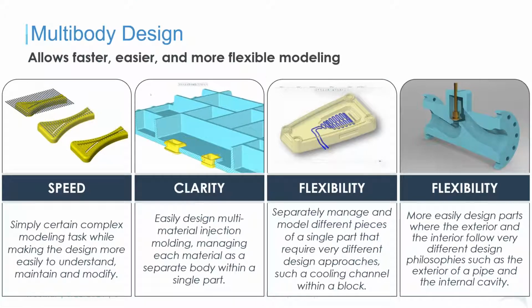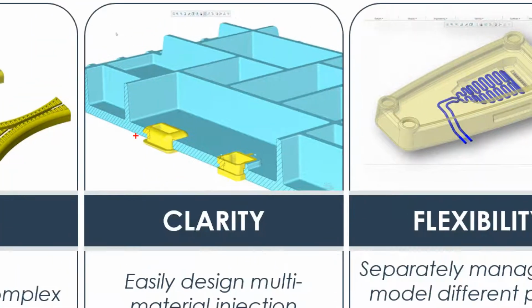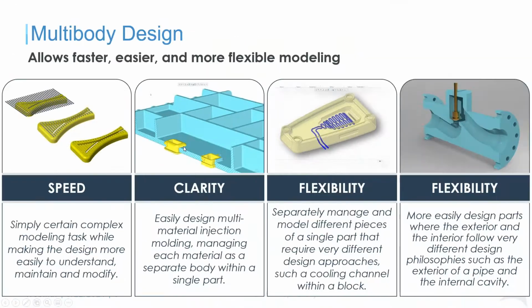Almost as a tool. And here's your multi-material injection molded part. So there's my overmold. I might want to create these as separate parts, and finally I may still want to have them as .prts. From a multi-body part, there's a way to simply create a new part. It'll do a copy geom of that and create a new part. So there's quite a lot of workflows. It's a lot more flexible overall for the different use cases, right?